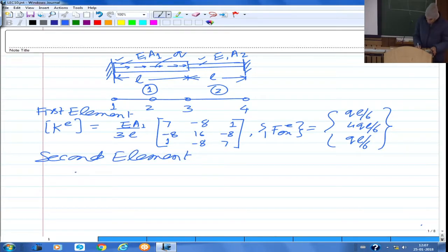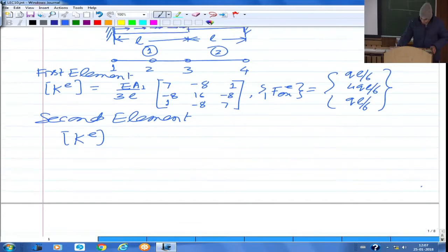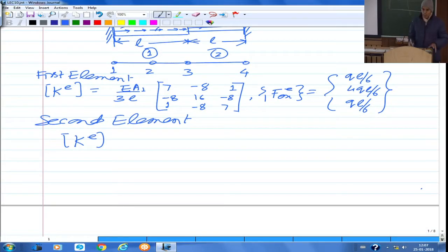in case of the second element, the element level stiffness matrix is, so like when you use a package software and different types of elements in a structure, depending on the element type, we'll call that particular subroutine and calculate the element level stiffness matrix and load vector, and depending on the problem, maybe other matrices or vectors, and then you will assemble them. So let's say the first phase is to calculate the element level matrices.